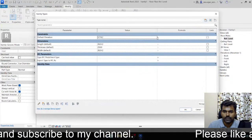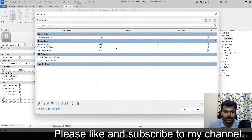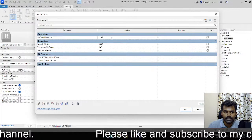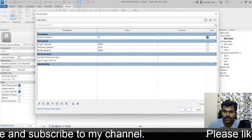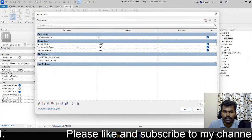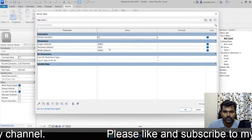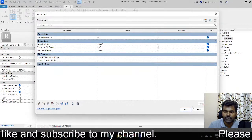Now go here, take length as 2 meter. These are two default values. You can change it later. Default elevation, let it be 0 and lock all these parameters. We are not going to change anything here now. Just say okay. What's the thickness? 250, or it's supposed to be 20, right? 20 or 25 max.